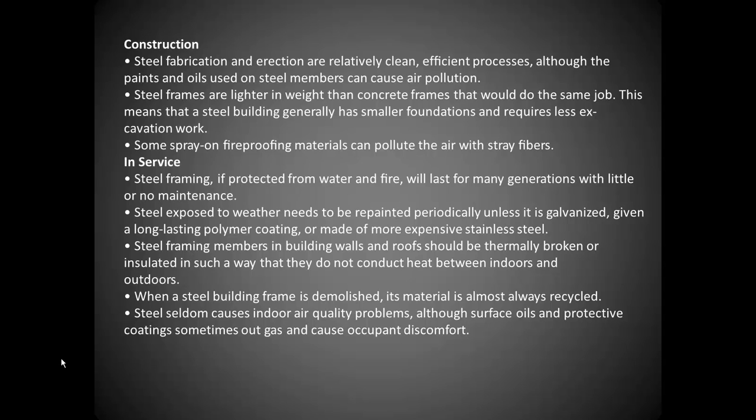If you look in Machine Tool Lab, for instance, it has a lot of single pane windows with solid steel windows that are not thermally broken, and you'll see frost build up on the inside, meaning that there's moisture being attracted to that cold steel and icing up. It just means that we're losing a lot of cold out through these. So having a way to thermally break that, and we're doing it now with our new windows and doors, but some of our older buildings haven't accomplished that, is relatively important.